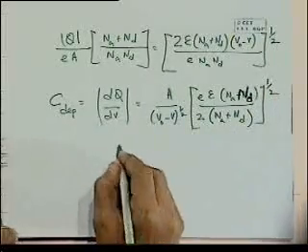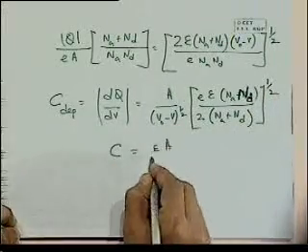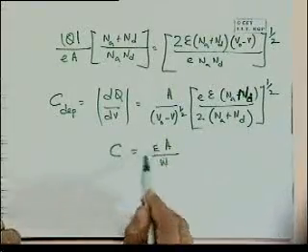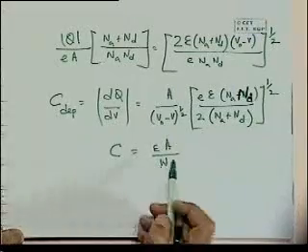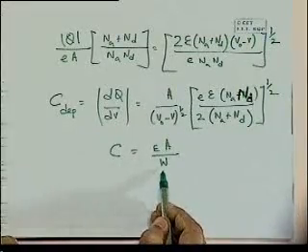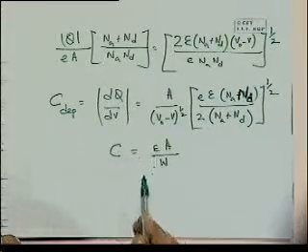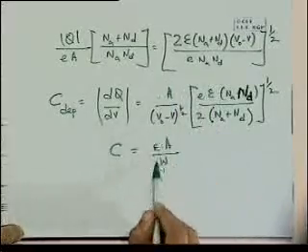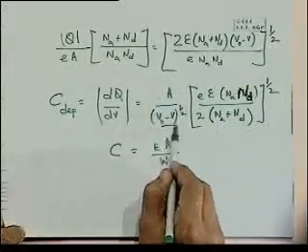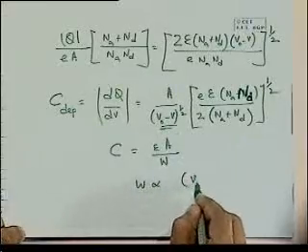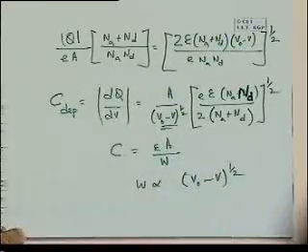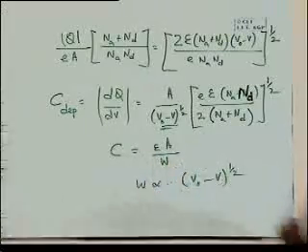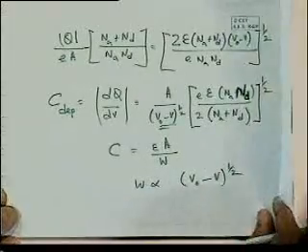which is very similar to the expression for a parallel plate capacitor, except that our W. This is the expression simply for a charge stored in a parallel plate capacitor. It's proportional to the area, inversely proportional to the separation between the plates, and the permittivity. That's the basic idea. So here also you've got the area, the permittivity, and then you've got a W term, which itself is dependent on voltage. So W is proportional to (V naught minus V) to the power half. So the junction capacitance in the depletion layer is behaving very much like a parallel plate capacitor.